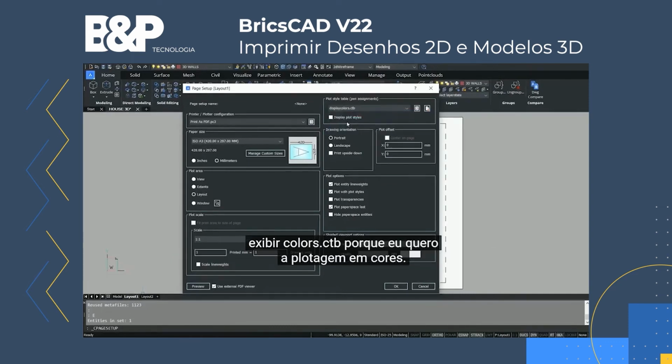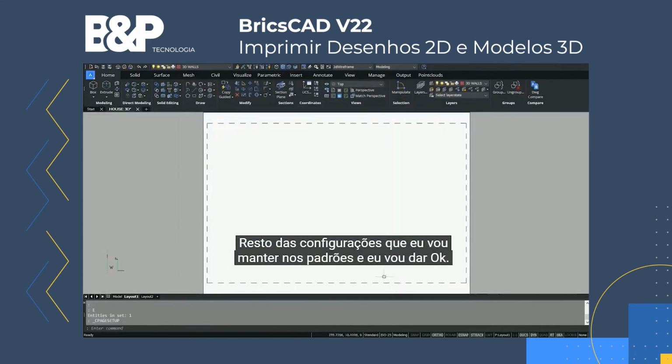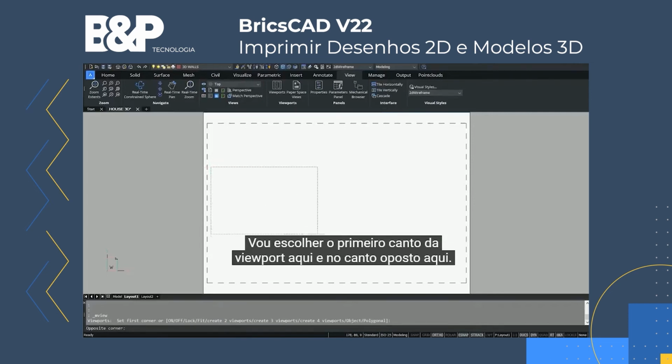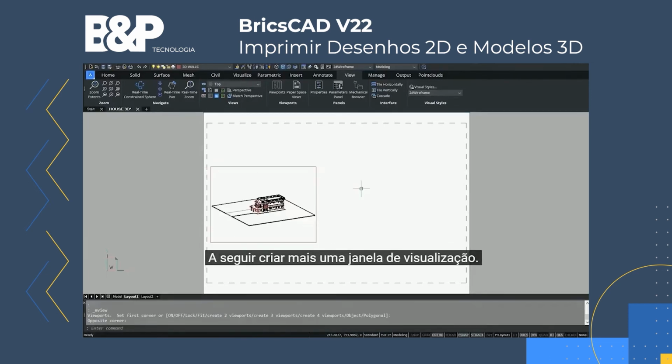Then for plot style table, I'll choose display colors.ctb because I want to plot in colors. Drawing orientation, I'll choose landscape. Rest of the settings I'll keep on the defaults and I'll give OK. Next I'll click on the View tab, Paper Space View. I'll pick the first corner of the viewport here and the opposite corner here.